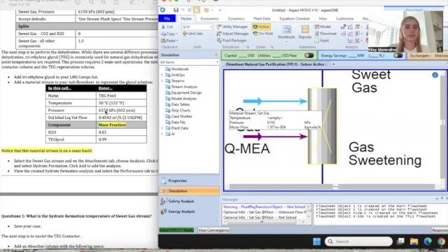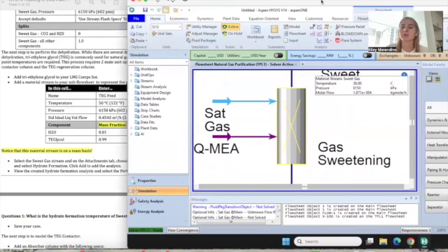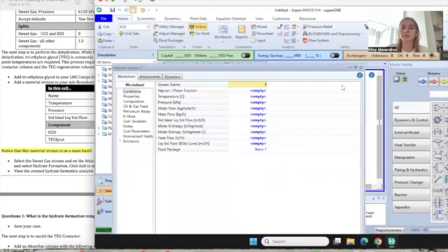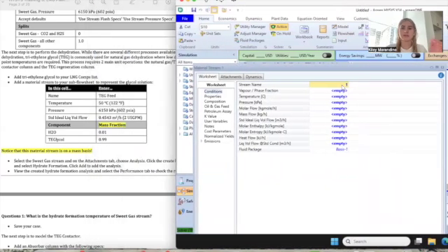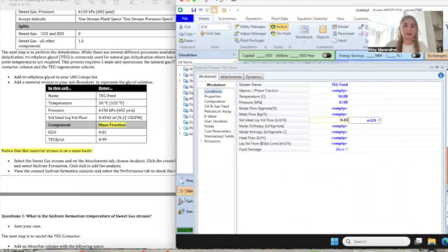So we're going to add a material stream into our subsheet to represent ethylene glycol. So come back over the blue arrow. We're going to name it TEG feed. Our temperature is going to be 50 degrees C. Pressure is going to be 6150. Standard ideal liquid volume flow is going to be 0.4543 meters cubed per hour.